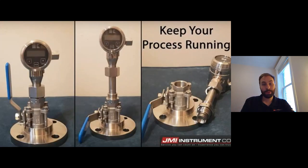You can isolate the pressure transmitter using a ball valve, in this case, and you can take out the diaphragm. If you need to replace the electronics or play with it back in the control room, you can do all of that, and you can keep your process running, because you can shut it off. You can isolate the pressure transmitter, the diaphragm, from the process using a ball valve. So every single time a pressure transmitter diaphragm needs replacing, which they do over time, you don't need to buy another flange. That's going to save you $100, $150 every single time you replace one, on top of the good pricing you're already getting. So something to consider.